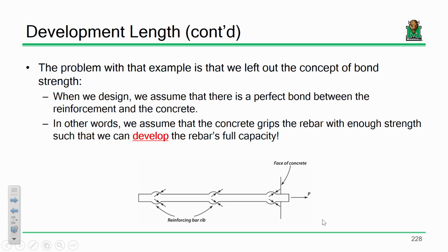So let me give you the concrete design analogy to what we just did. Imagine that this was a big wall of concrete, and I had a piece of rebar embedded inside the wall. If the rebar was only embedded this far, I could probably easily yank it out, right? Whereas if the bar was embedded, say, 1,000 miles into the wall, that's not happening. I'd have to be from Krypton to make that work. The reason why is because the farther that embedment occurs, the stronger the grip.